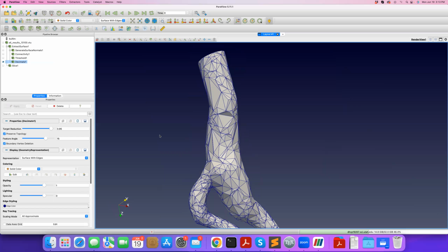So there's another feature that doesn't cut through it. So by the way, if you want to cut through it like that, so sharp cut through your geometry, and you want to convert your mesh back to tetrahedral mesh, you can do the filter alphabetical and do tetrahedralize. So now it will tetrahedralize your mesh once again. Or if you have a surface mesh, there's the option triangulate, which will, when you crop the domain and you have like your triangles get cropped in between and you no longer have triangles at the boundaries that you cut your domain, you can apply the triangulate filter and generate triangles.